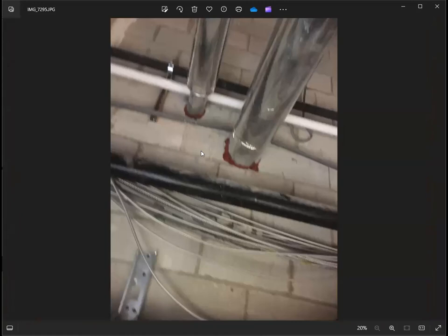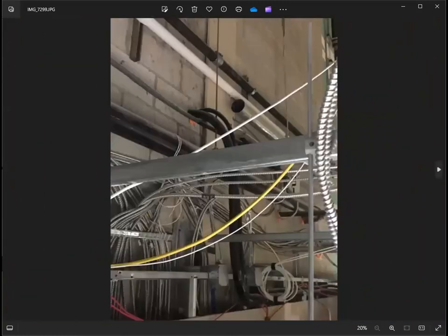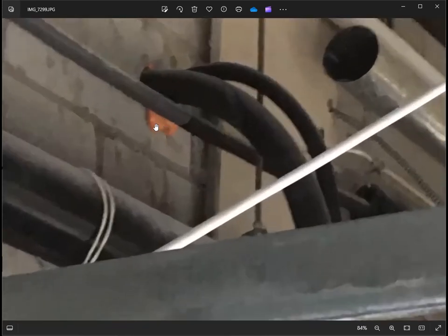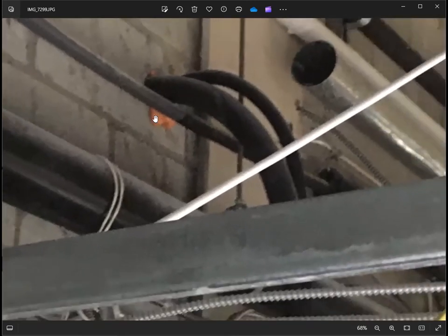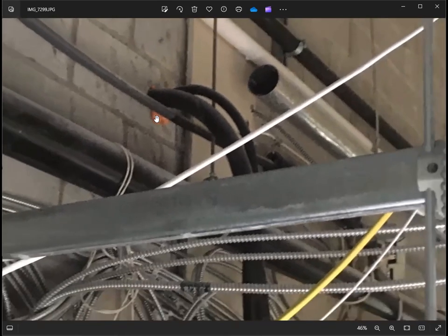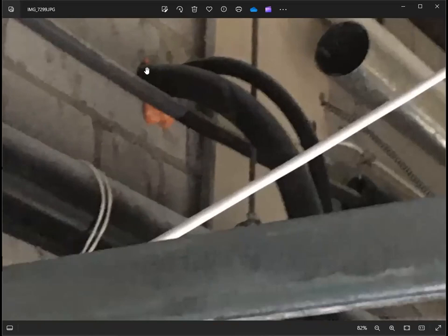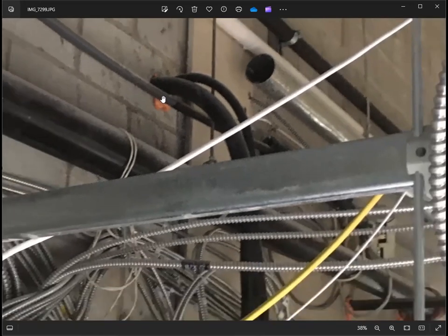This is another penetration in the wall for the exhaust ductwork, complete with firestopping. And the refrigerant piping, this is the yellow stuff. I think this is a backer rod. This is not acceptable as firestopping material. You could use this backer rod to minimize the gap between the wall penetration and the piping, but you also need to put the red stuff, the approved firestopping material.